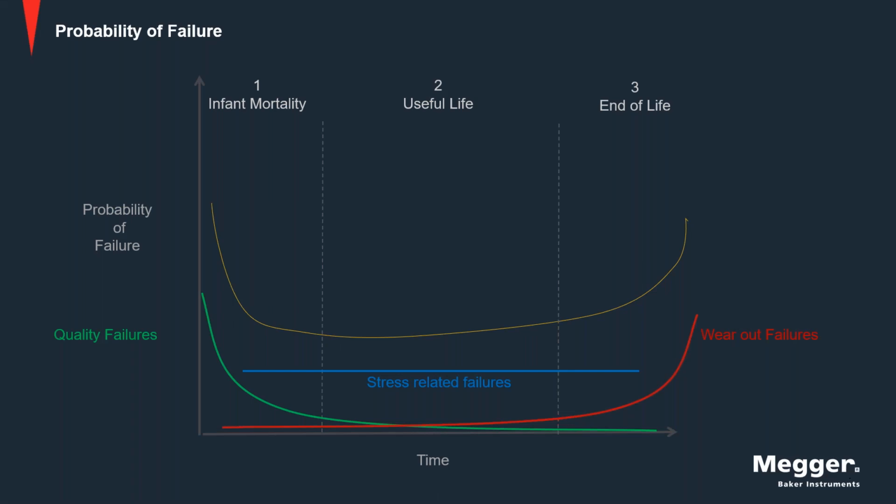He talked about the bathtub curve and the probability of failure: when you first receive a motor in and you put it into an application, we expect a high probability of failure then, the infant mortality. Things due to manufacturing defects and rework faults become apparent when you fire the motor up. Maybe just how the motor was put into the application. It wasn't aligned properly. It wasn't connected properly. All those things play into why there's a high probability of failure in the beginning of time.